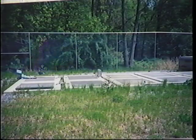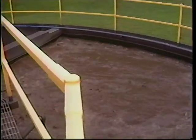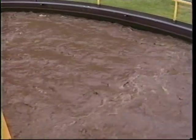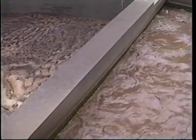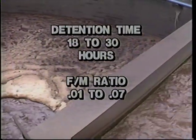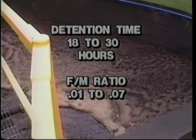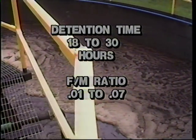The extended aeration activated sludge process is most commonly associated with package plants. The configuration of the extended aeration system is similar to the conventional activated sludge plant, except the detention time in the aeration tank is 18 to 30 hours with an F to M ratio of 0.01 to 0.07.